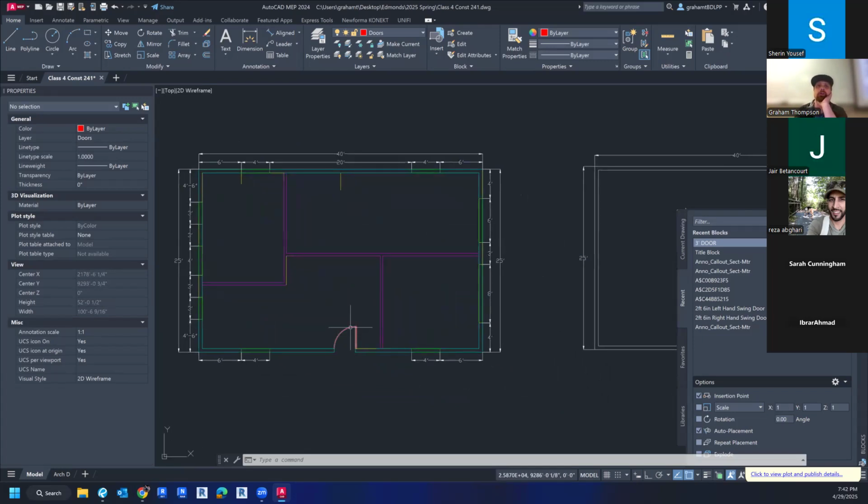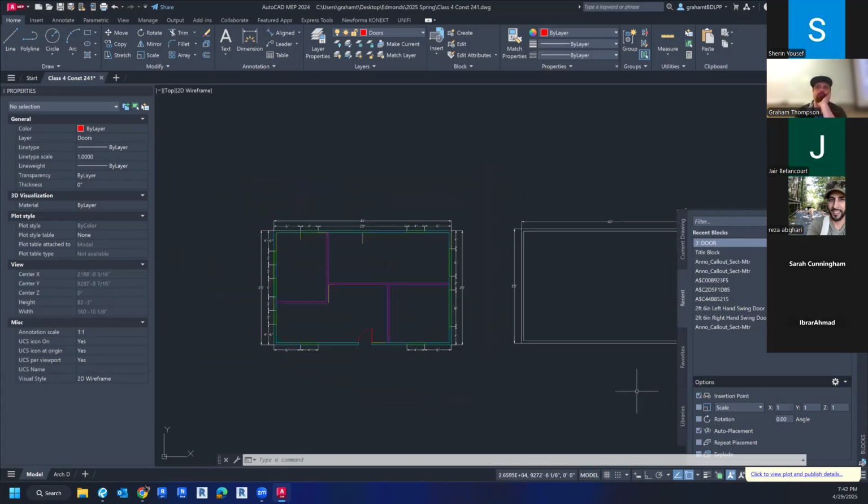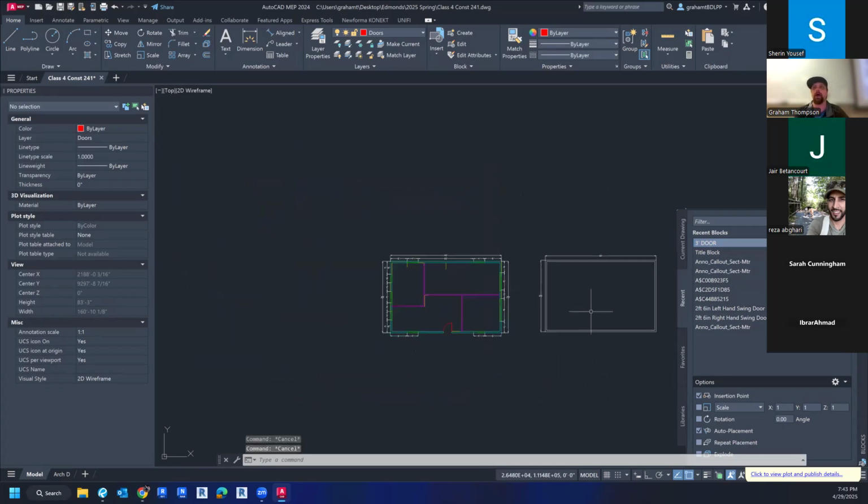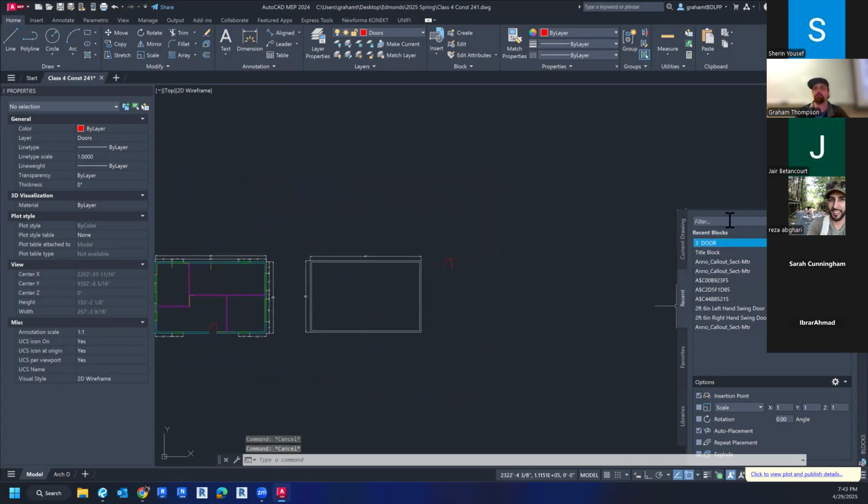And it's hard to manipulate, because instead of something you can just drag from your block palette, you have to go find it, then use your move command, select a spot, and move it to the right location, when you could have just dragged it, clicked once, and it was done. Okay. So having the ability to bring something out of that block palette is super, super handy.